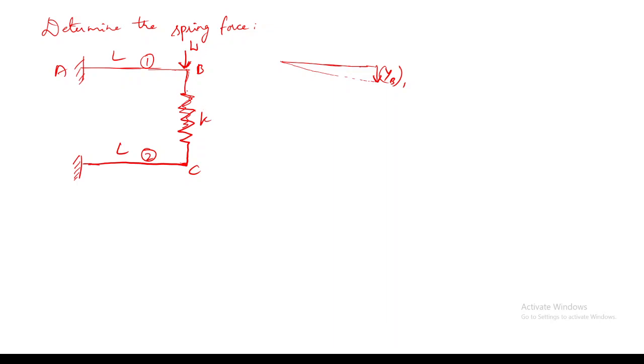It will cause equal deflection. Yes, equal deflection. But you are having a beam at the bottom which is attached to this same spring. Due to this deflection it will cause a reaction like this, Rs, for the beam. If I draw the free body diagram of the beam, it will be something like this, whereas for the spring it will be something like a compression.